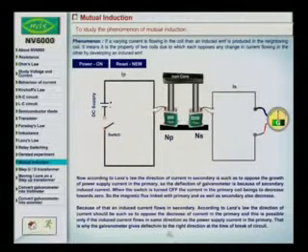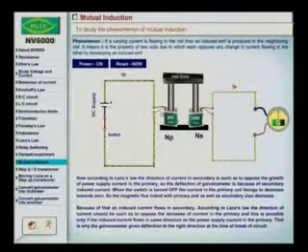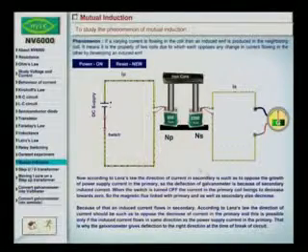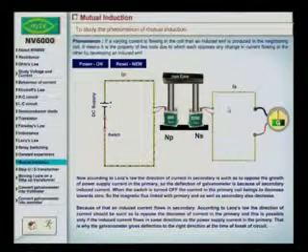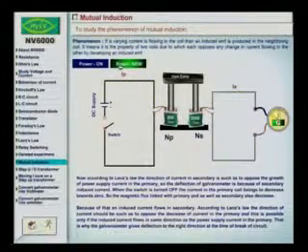That is why the galvanometer will give deflection in the right direction at the time of break of circuit. Let us see again and visualize the effect. Right now only one coil is given supply. So due to that, the secondary coil has an induced current, but that induced current is in the opposite direction as per Lenz's law, right? And the galvanometer deflection you can see.